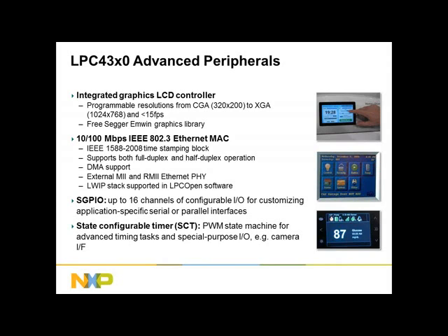We have a tool in our software that allows you to create a little state machine and really custom make any timing interface that you want. It's so flexible, in fact, that one of our clever apps engineers, based out of China, figured out a way to have a VGA camera input using the state configurable timer. So we have kind of competing camera interfaces, one using SCT and one for serial GPIO, which kind of highlights the flexibility of these peripherals.